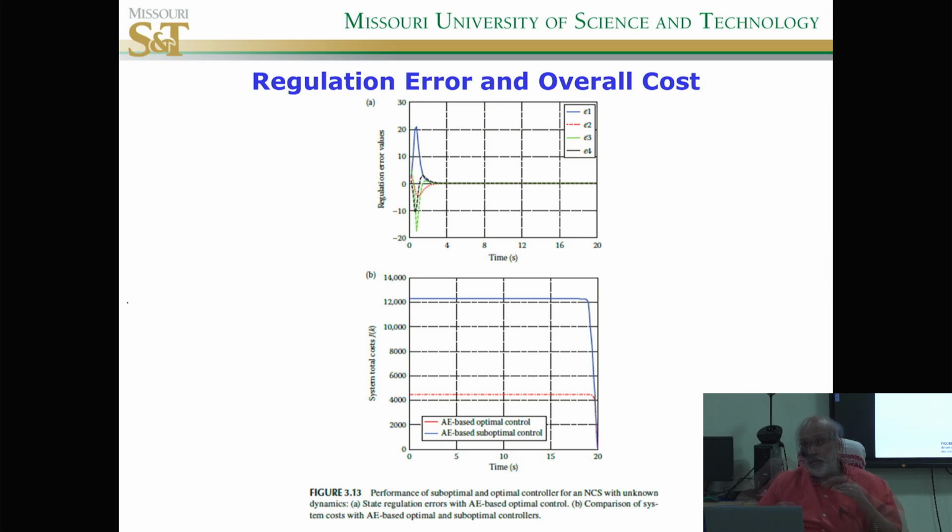But why do you use the suboptimal? Because suppose you cannot compute it in real time. Let's say you are unable to compute because the gains are changing with respect to time. Then what you can do is, a lot of industries do this. They run this code offline, and they find out the steady state value of the gains after they converge. They use those steady state values in the control input.